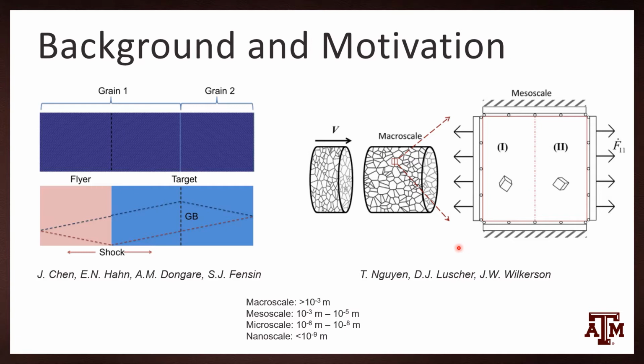To put this difference into perspective, the simulations done by Chen et al. used 15 to 20 million atoms. My simulations, modeled off the image on the right, are run on 20 to 25,000 atoms, 3 orders of magnitude smaller and faster. The goal of this study is to find a faster way to test cavitation strength of materials to aid high throughput design. I studied void nucleation behavior in a mesoscale simulation, like that shown on the right, to find the cavitation strength.